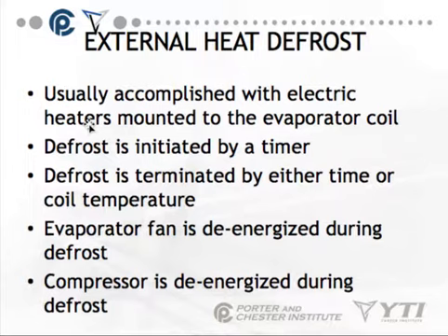External heat defrost is most often known as electric defrost. I just want you to have both terms because you'll see it sometimes both ways. It's usually accomplished with electric heaters mounted to the evaporator coil. Defrost is initiated by a timer.